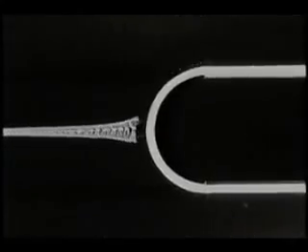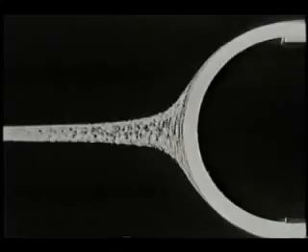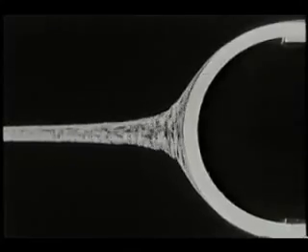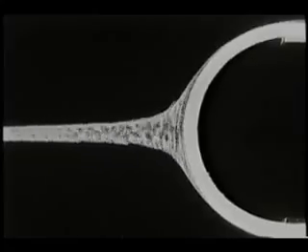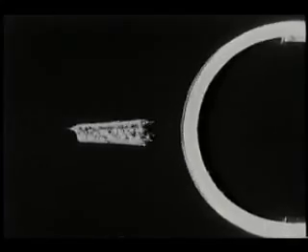Here is a streaming flow past the blunt body with a central stream tube marked by hydrogen bubbles. The widening of this stream tube tells us that the flow is decelerating. The singular point where the central streamline reaches the nose is a stagnation point. The speed is zero there. On both sides of the unique stagnation streamline, the fluid decelerates, but not to zero speed, and then slides around the sides.